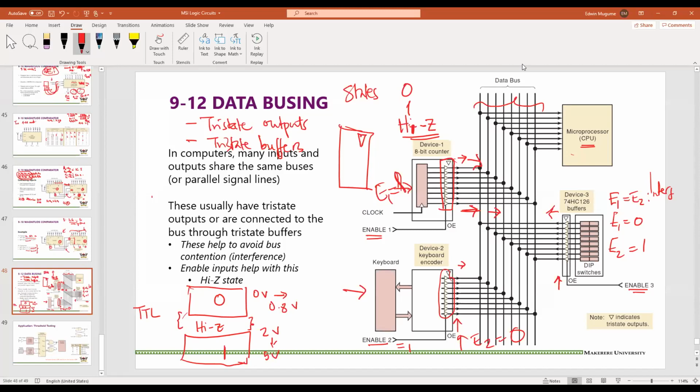Does that mean that we can have an infinite number of circuits using the same bus, or is there a limit? It is an interesting question. I think an infinite number of circuits means that you would need infinite time for all of those circuits to have access, for instance. So maybe what you want to say is, can we have a large number of circuits sharing the same bus? And I think the answer is subjective. There is no clear limit on the number of, for instance, registers that could use the same bus. This could be a very large number. It could be 1 million registers using the same bus.